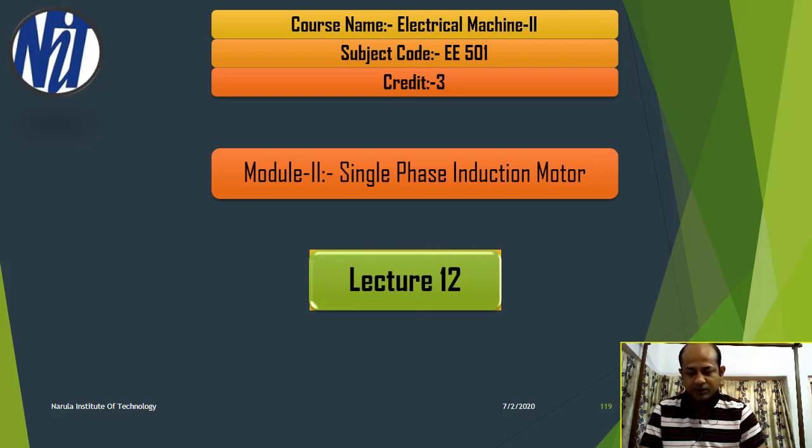In our last lecture classes, we were developing the cross field theory so that we can show how the interaction of different fluxes, or different EMF which is responsible for the production of these fluxes, produce torque in a single phase induction motor.